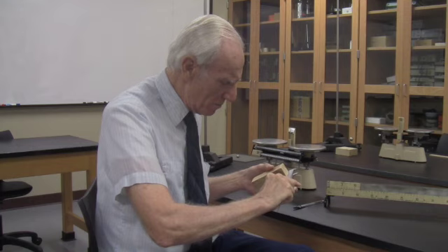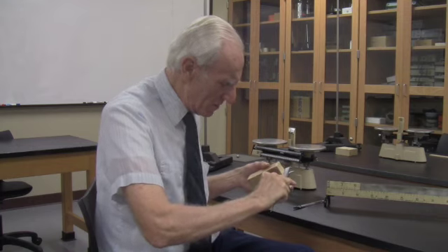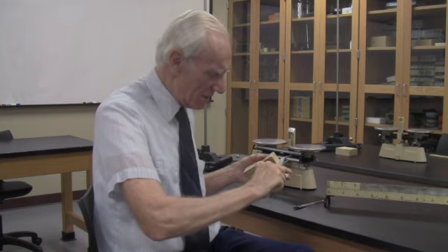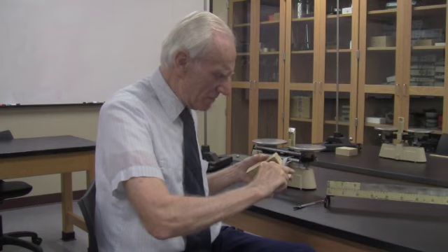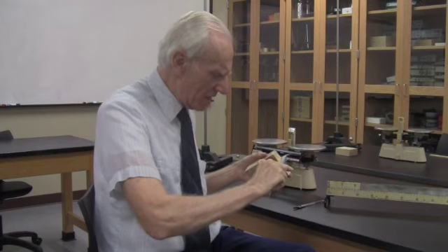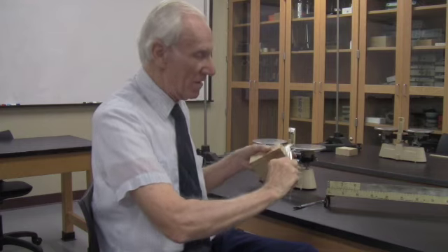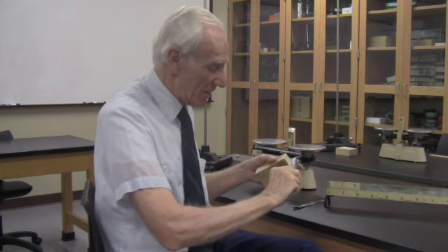look towards the end, the high end of the scale, and it seems to me that the first mark past 8 is the mark that lines up best with the mark above it, so that would be 3.682. Each one of those little marks on the scale is actually 0.02 millimeters. Again, that's how accurate it is, or potentially accurate it is.